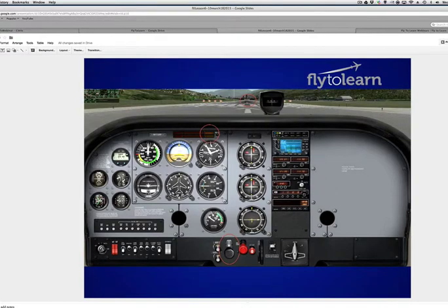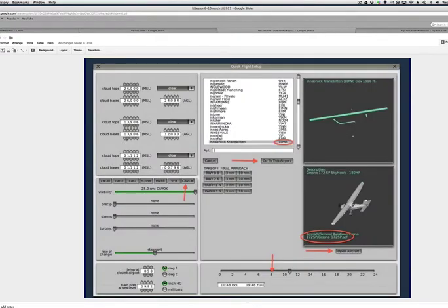All right. So you go to quick flight setup before you jump down to here. That's where you set your airport to Lawi. For the most part, that's what you want to do. Then you want to go to General Aviation Cessna, where you take that airplane right there, open the aircraft and use it. We tend to use the Cessna 172, and we use a King Air in the first 5 lessons. And you're going to set your air to clean. Don't have them flying through storms, etc.